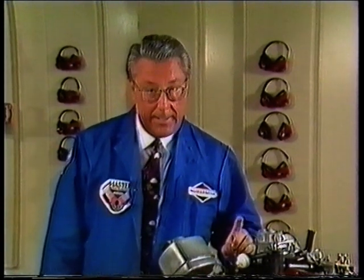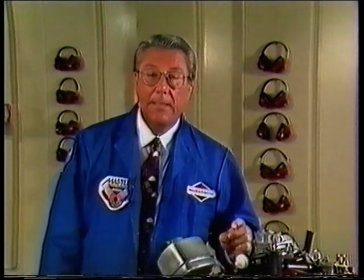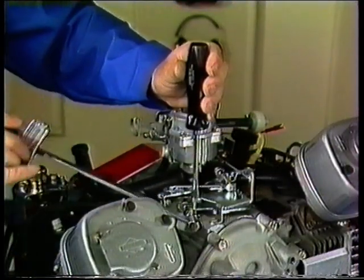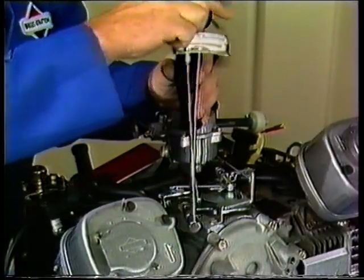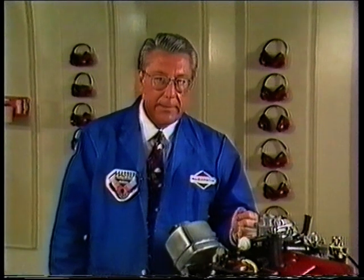This is where your understanding of carburetor theory really comes into play. Separating a possible governor problem from a carburetor problem can be different in each complaint. To begin, you'll need to make sure the governor system is adjusted and operating properly. The next step is to make sure the idle mixture is properly adjusted.